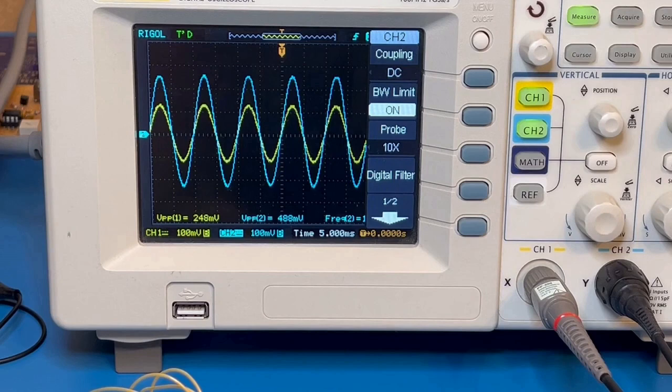This is partially due to the accuracy of the scope, partially due to errors in the gain setting resistors, which are not precision resistors, and partially due to other setup-related issues like EMI in the setup causing voltage spikes being picked up by the scope and artificially increasing the peak-to-peak voltage measurement. Both channels are on the same volts per division, which is why channel 2 looks about twice as large as channel 1.